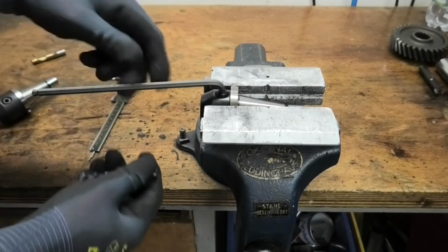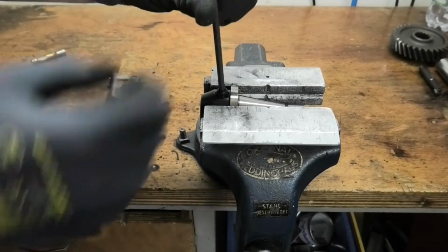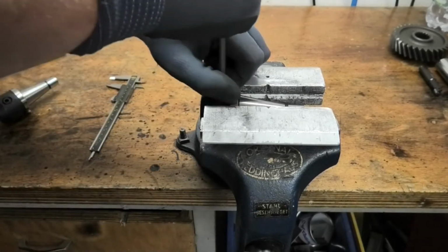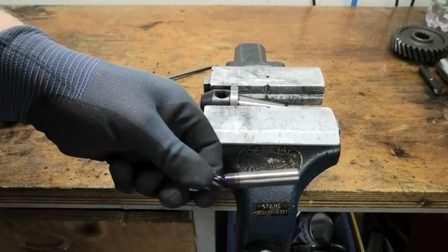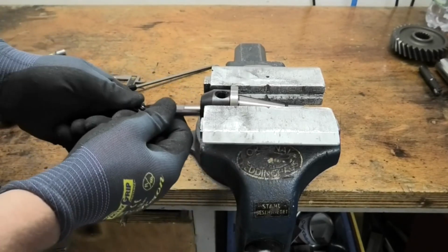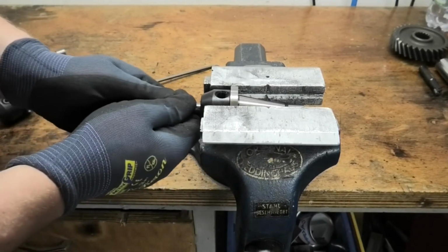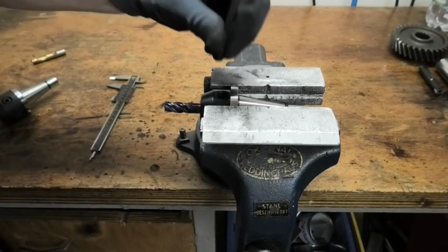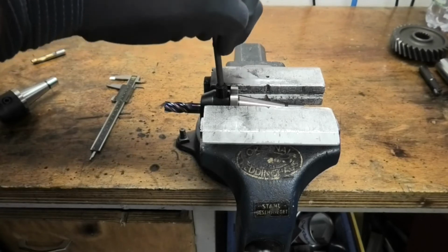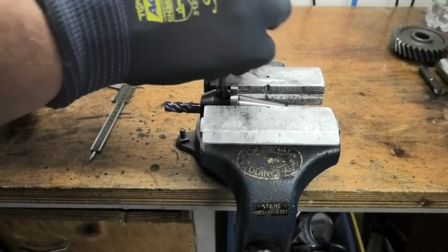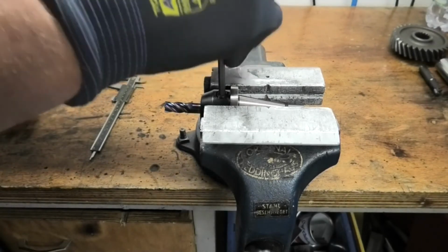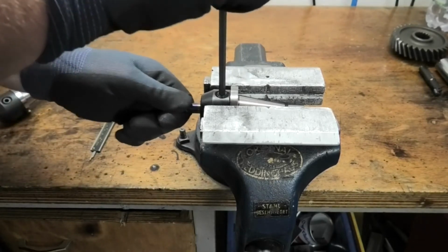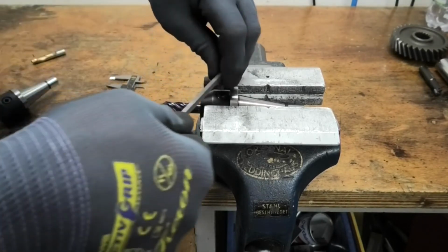My milling machine has a 1.5 kilowatt synchronous motor. In addition, I have installed a German Wittenstein planetary gear with 1:3 ratio, see our video 140. In this video another gear brand was mounted. This combination of powerful electric motor along with a planetary gear already has a lot of torque, and Weldon chucks transmit much higher torques than collet chucks.